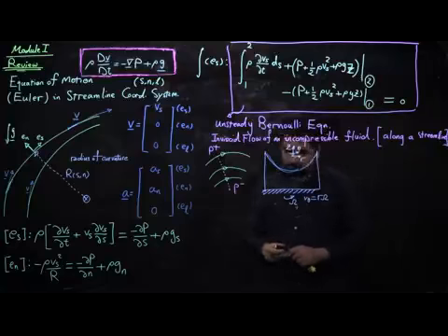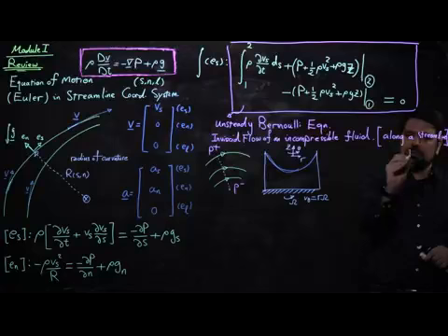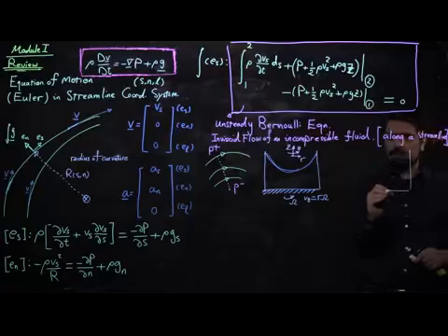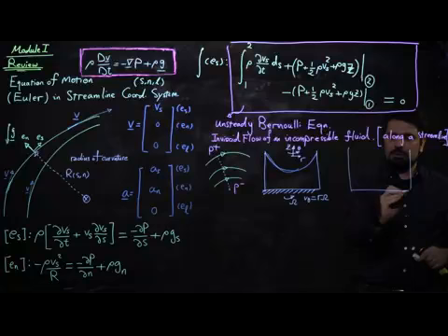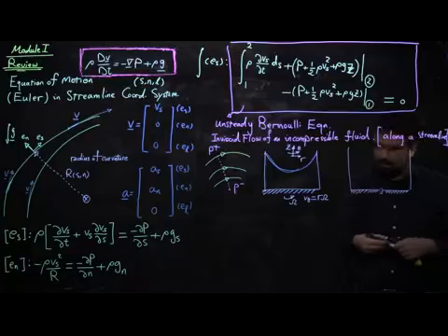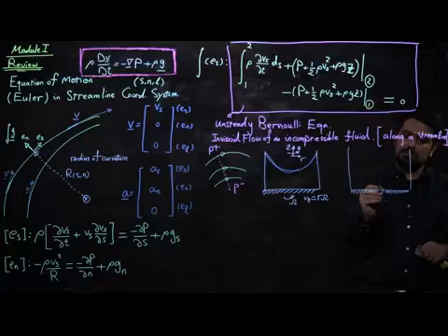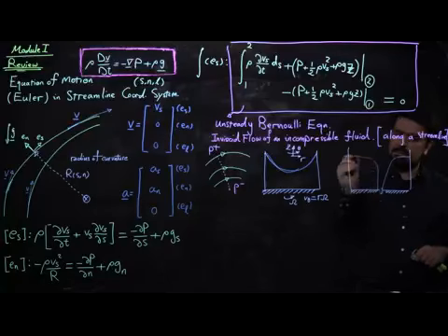Exactly similar kind of shape of streamlines, circular streamlines, show up when we looked at the problem of ideal vortex, which happens when, for example, you have a tank and at the center of it, all of a sudden you open an orifice, and with some initial angular momentum, you let the fluid elements get out of that central drain.